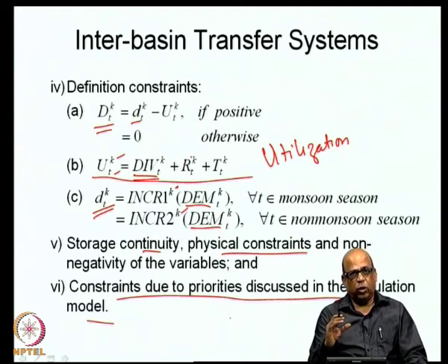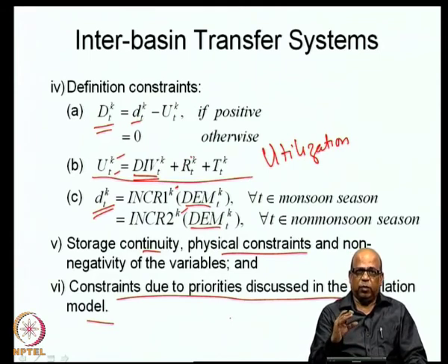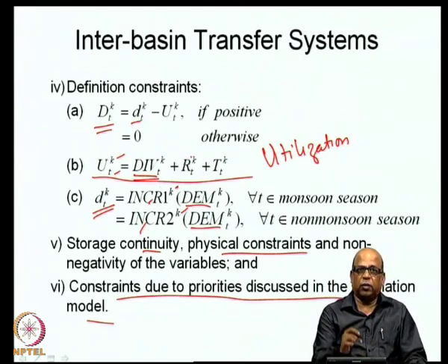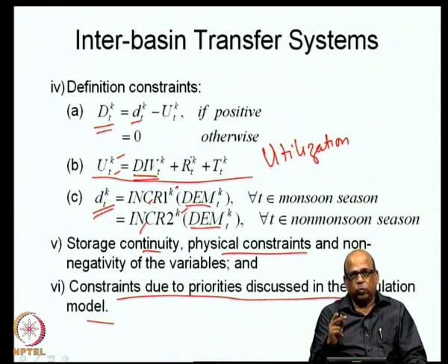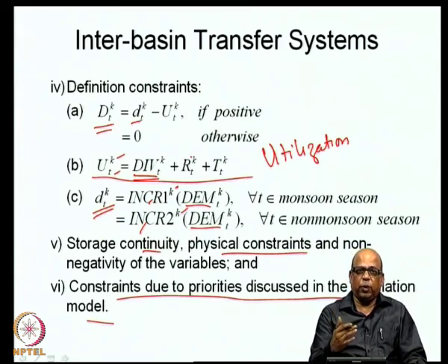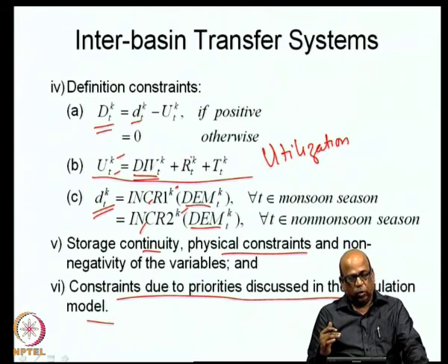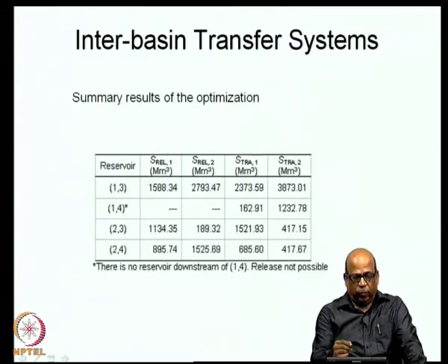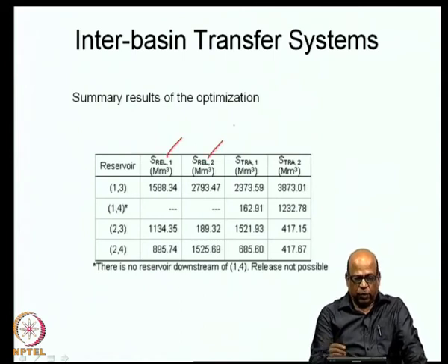So, the simulation model that we had built earlier, we will now formally put it as an optimization problem, where there is a search over all these decision variables, STRA1, STRA2, SREL1, SREL2 at all of these reservoirs, and INCR1, INCR2 at all of these reservoirs. So, the nonlinear programming makes a systematic search and then finally gives you the optimal solution in terms of what are the SREL1, SREL2 at each of these reservoirs.